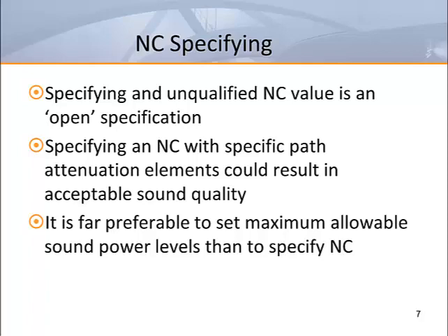We refer to such an unqualified NC level as an open spec because it leaves the door open for misinformation and misrepresentation. An unscrupulous vendor could say that they can meet the spec requirements because under some circumstances they might. For instance, a fan-powered terminal supplying air to a warehouse full of pillows. Now obviously, that wouldn't be very honest to make such an assumption. Unfortunately, many people in our industry won't ask questions when faced with too little information. It's often simpler to throw out a number rather than stir up a debate.